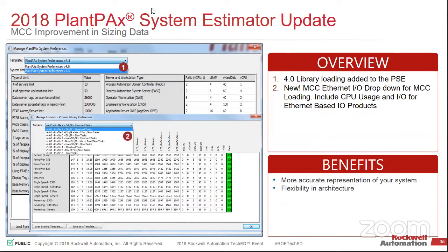It might not be a flat network. It might be dividing your power from your standard control. You need to take a look at the network loading when you add an MCC to it and see if it adds to it. I think it's more taxing. Now, someone else might say differently, but I've seen more loading on an MCC. It can be addressed. It's not a big deal, provided you design the network around it.